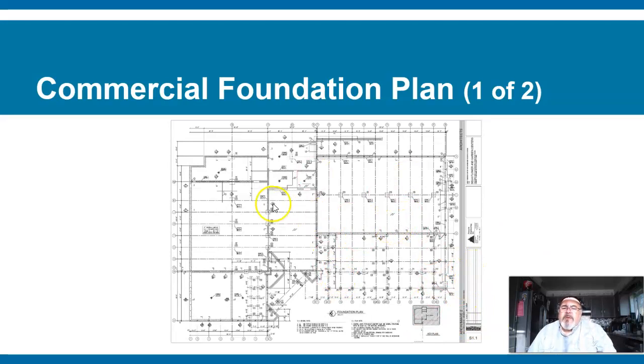Now I say measurements because when you're building the footing, it'd be different measurements, and also when you're estimating the materials, it's different measurements. What do I mean by measurements? There were different shapes of a certain type of foundation. It had a footing and a wall, and maybe the wall is taller and has more steel in it, or maybe the wall is shorter and has less steel in it. So you would keep track of the lineal footage of the different types of wall.